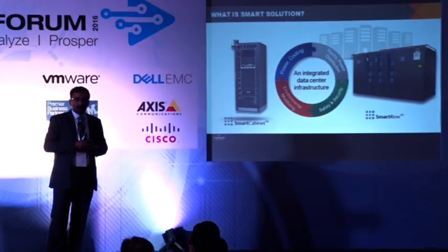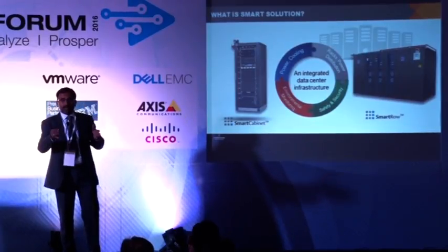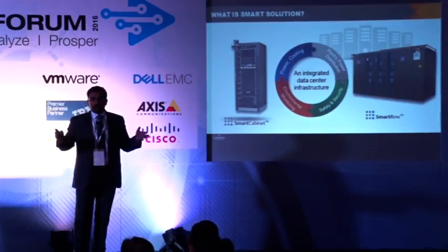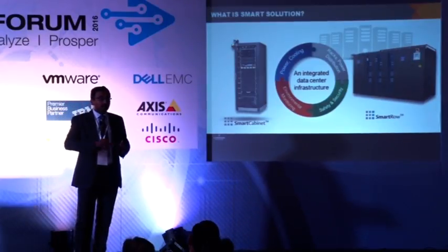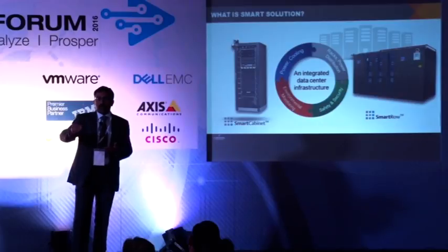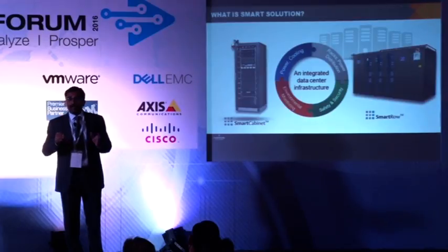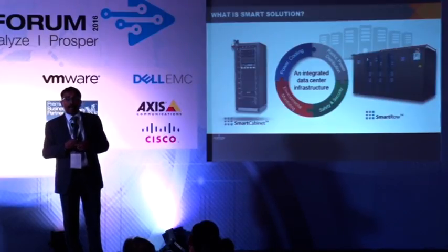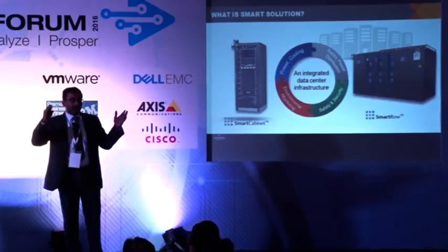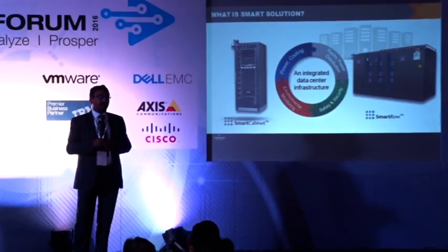So that is what is happening, the typical split AC, wall mounted kind of ACs have been put. And let me tell you, they were perfectly fine when the IT loads were in the range of around 1.5 or 2 kilowatt per rack. But with virtualization coming in, with blade servers coming in, a lot of other storage devices coming in, that per rack load from 1.5 kilowatt is gradually moving to 3 kilowatt, 4, 4.5, 5 kilowatt. And a few of the customers are really stumping us by telling us that they need 10, 12 kilowatt per rack. So when that kind of a change is happening, those wall mounted split air conditioners are not efficient or effective to provide the cooling.